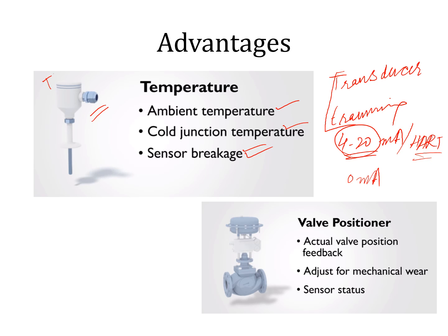Let's say T106 is the tag number of this particular transmitter, and we can have an additional sensor near it, and we can also measure ambient temperature near this transmitter, and that can be used for the cold junction compensation for thermocouple kind of temperature transducer.